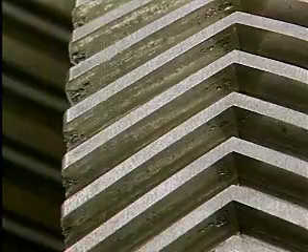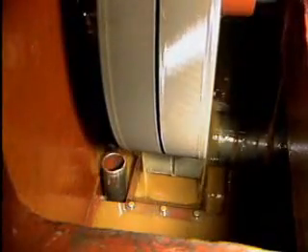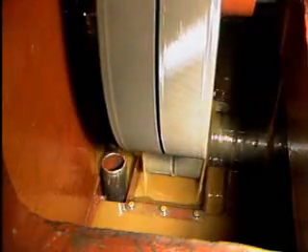The contaminant may also cause foaming of the lubricant, which can reduce the flow of lubricant to parts of the gear set, and this condition can reduce heat removal. You can prevent contamination from causing excess wear by replacing the lubricant at regular intervals. If a lubricating system does not lubricate all of the gear's tooth surface before they mesh, overheating and excessive wear may occur.